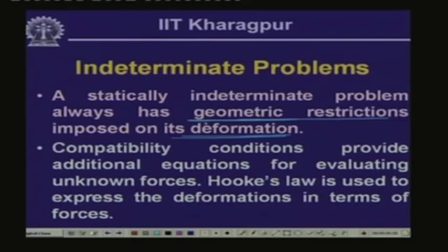So, we have seen that we have 3 equations of equilibrium, which are statical equations of equilibrium. Over and above, if we write down the equations of compatibility which arise from these geometric restrictions for the deformation, this equation of compatibility along with the equations of equilibrium will lead us to the system of equations from which you can solve the unknown reactive forces in the indeterminate system.